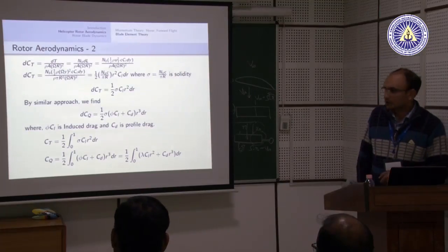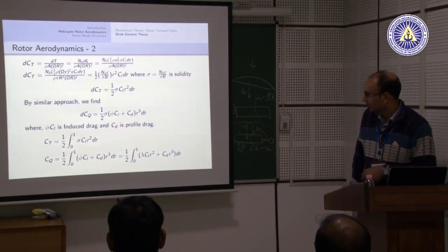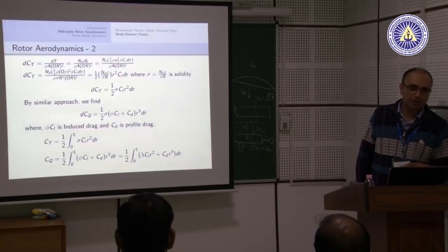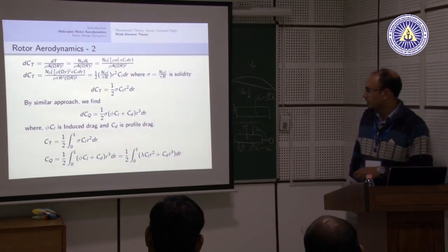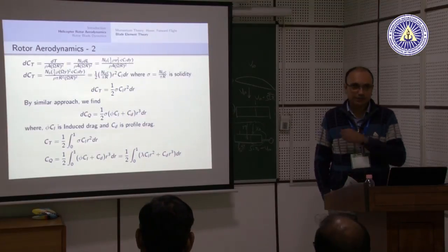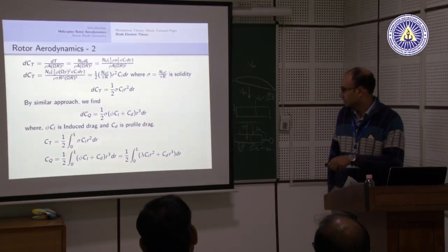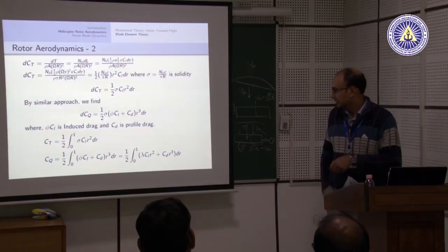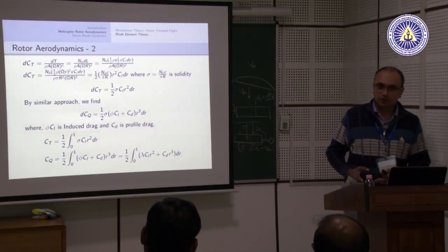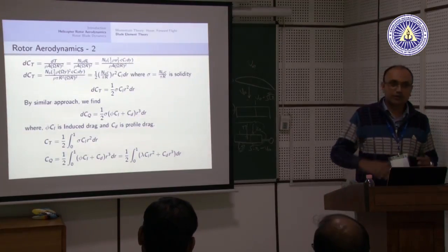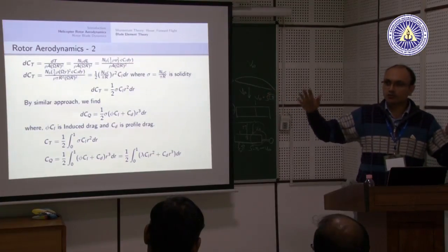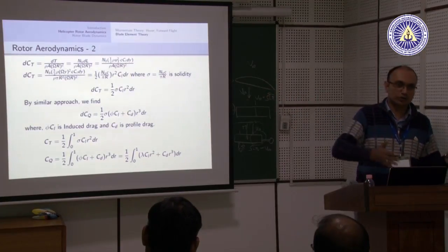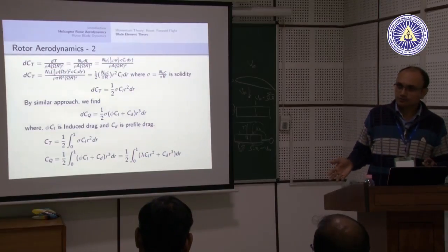Okay. So, normally to get this lambda, either we use the momentum theory which we saw earlier, which is the simplest possible approach, or I can use more complicated things. I will give you one example of a slightly more accurate way of calculating this inflow, because in momentum theory my inflow is uniform everywhere in the rotor, it is constant everywhere, the same amount of induced velocity is produced by every part of the rotor, which is not at all true.